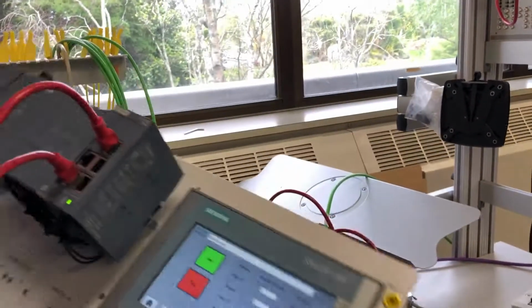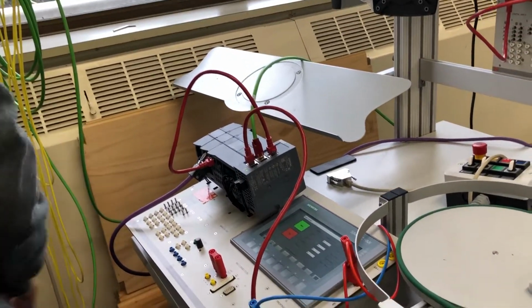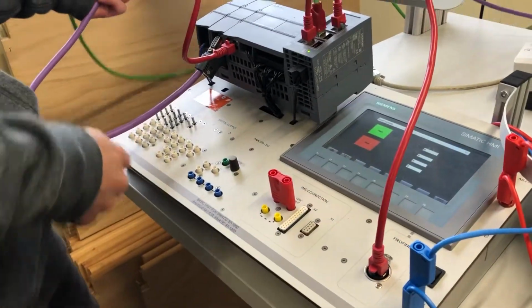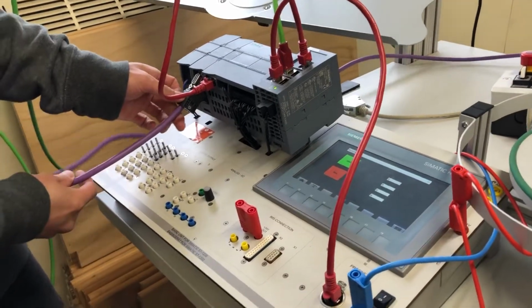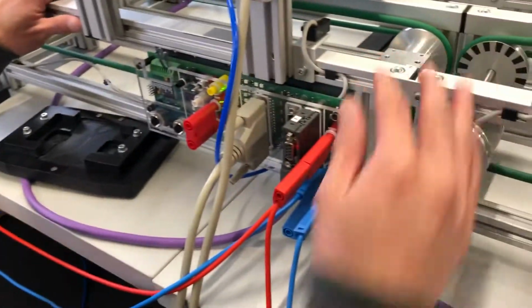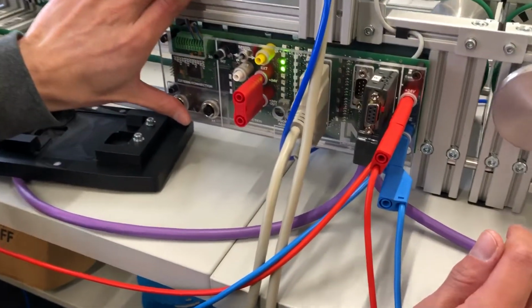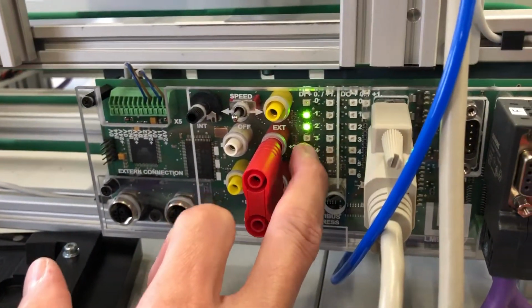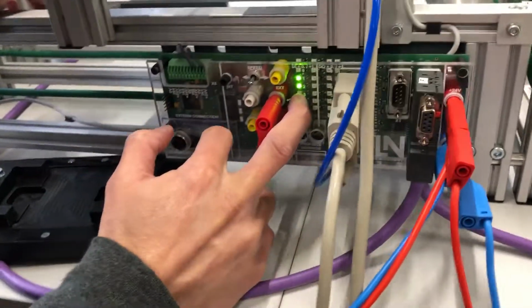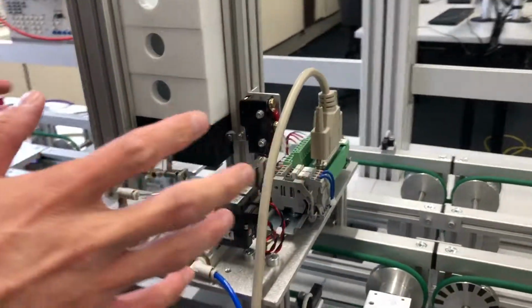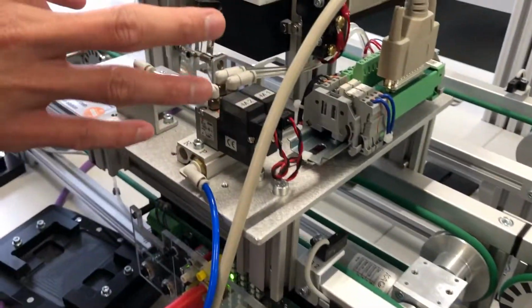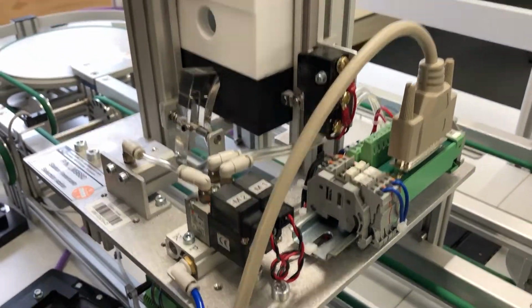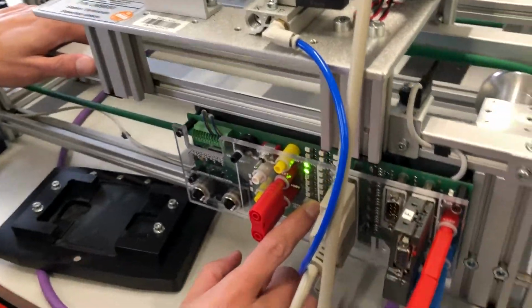And for the connection between the master PLC and the slaves, I use a Profibus connection. You can see the cable here connecting the PLC in series with all the stations. In each station, you've got a unique Profibus address, see here, and also the input-output addresses as well. The inputs and outputs represent all the solenoid valves and the sensors in the station, so we can control all the components by IO address in our programming. Come here, I'll show you my program.